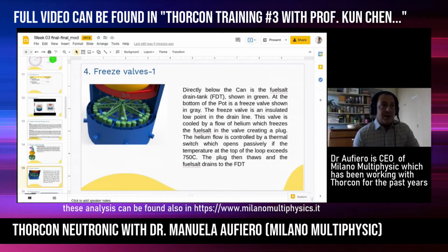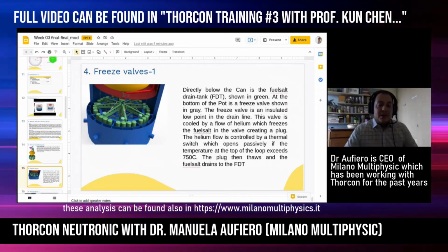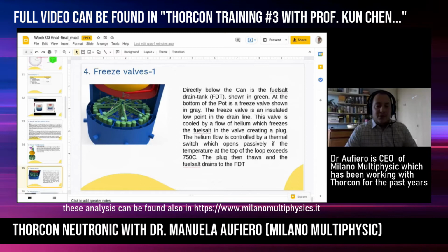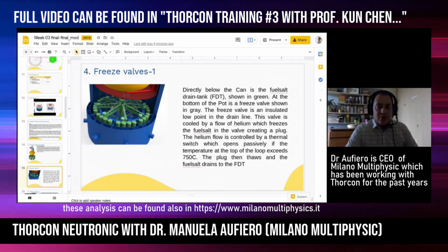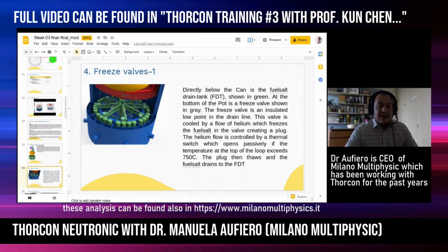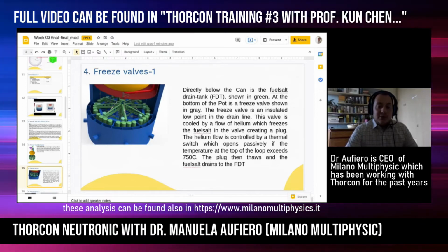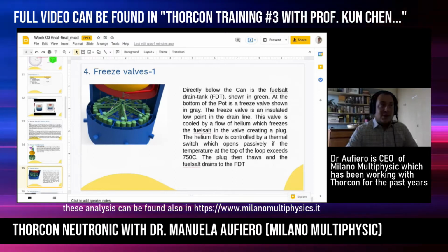As soon as this active flow of helium is interrupted, either voluntarily or due to the loss of available power, the heat in the heat capacity surrounding the valve starts to flow through the valve to the plug of solidified salt until the salt melts and the valve is open.